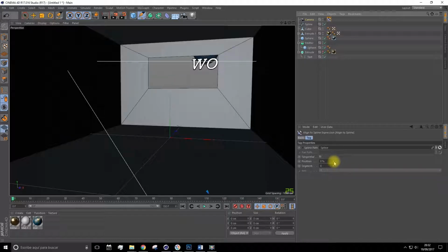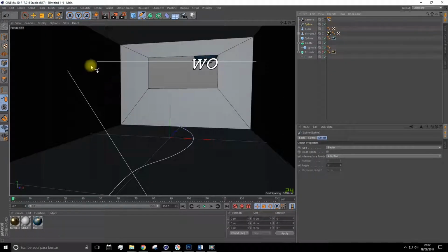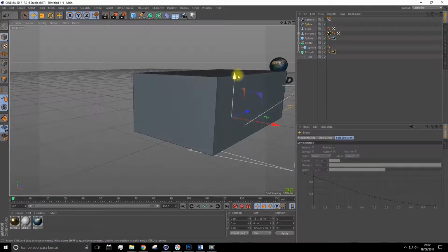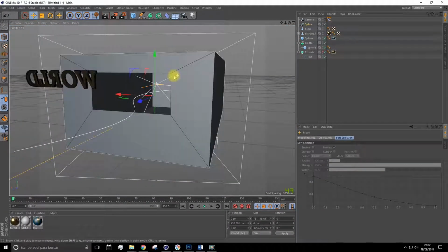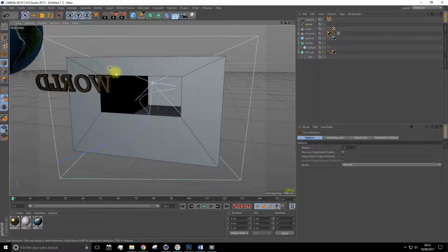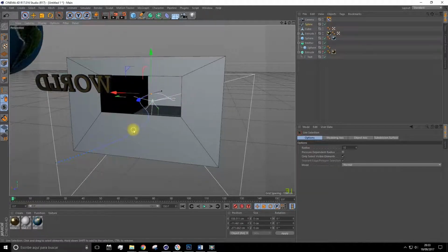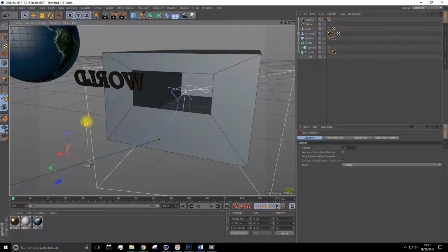In position right now it's 0%, but if we move this, you see that the camera moves on the path. We just need to move the spline up slightly. We need it to go through the window. We'll also adjust the points so that some are lower down and some are higher up. For example, the starting point, we could place it here. This one a bit higher. And the same for the last point.